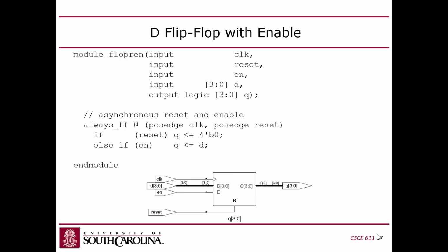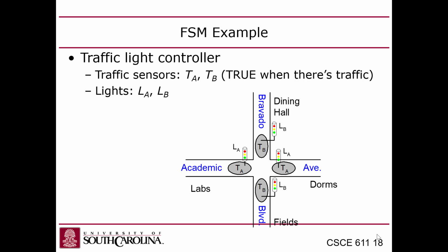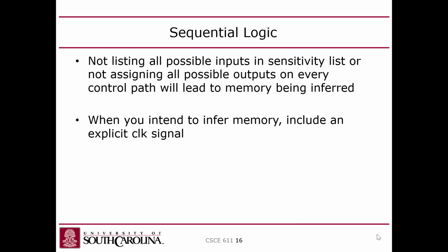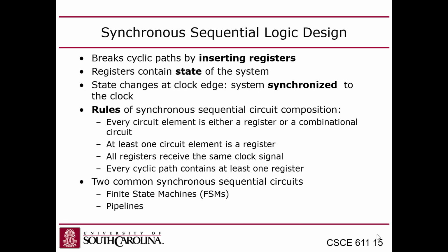Make sense? So anyway, the point is that I think we should be okay as long as you use the always_ff to make your flip-flops and your always_comb to make combinational logic. Okay, so let's talk about finite state machines. I mentioned, so sequential logic is what you use for finite state machines and pipelines.